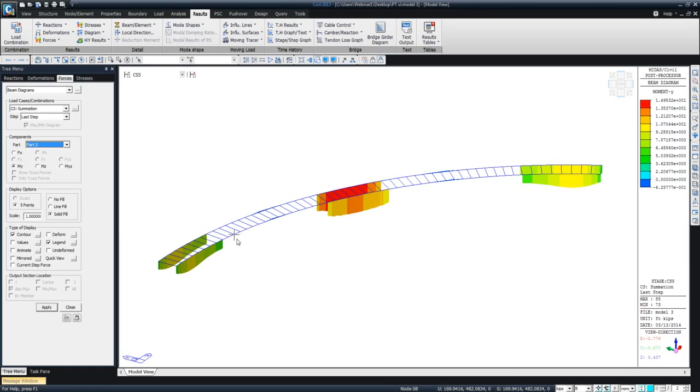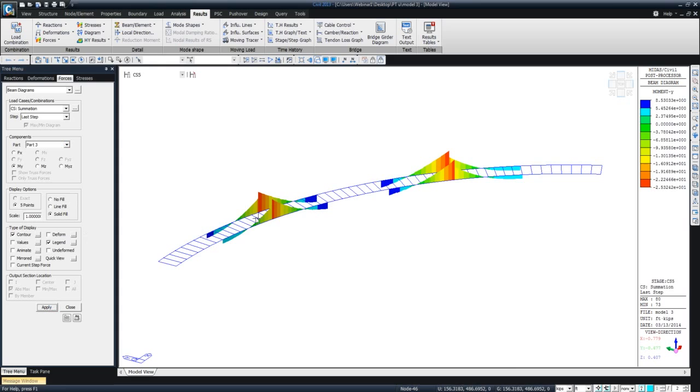And part 2 for other sections is the girder here, or is the deck, and part 3 is only available in certain spans. So you can see how the bending moment is shared by different parts of the composite section. But if you look at the overall picture as total composite section forces, you can use these forces to design your sections.